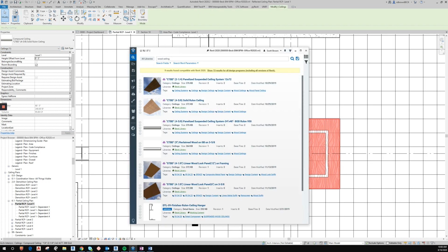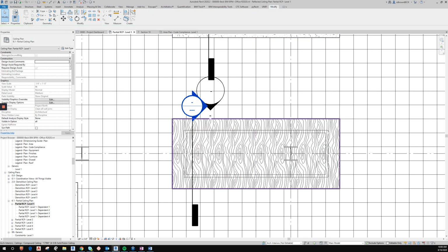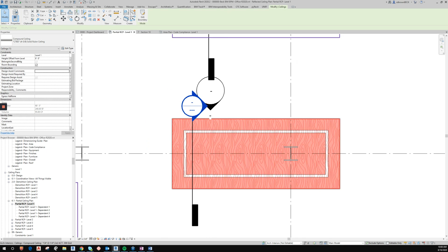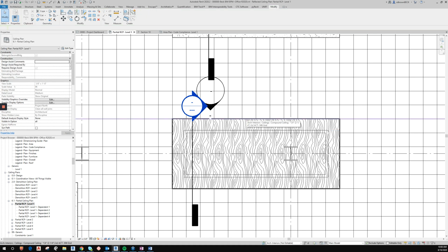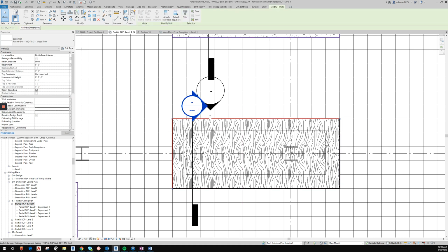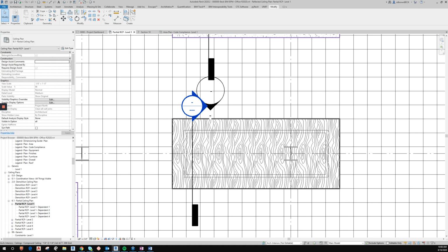Okay, so now we have our wood ceiling. And remember, in the previous video, the reason I like to do it by pick is if we need to adjust this, we can just do it by moving the walls. We don't have to edit the sketch anymore, which is really helpful. And you can make some pretty significant changes to this as long as it doesn't require any additions of line segments. You can do quite interesting changes with that. So that's about it. Let's take a look.